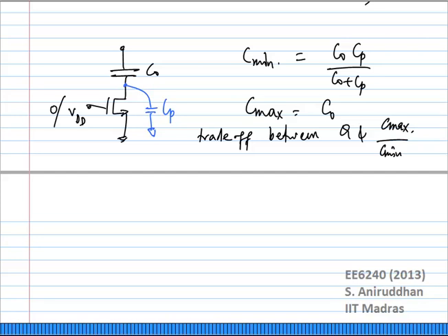The bias, right? You are more or less done with the VCO core. Now you need to design the bias. What do you do with the bias? Okay, and that's it, right? NMOS or PMOS current source, that's it. Is that all? Unfortunately, it's not that simple.